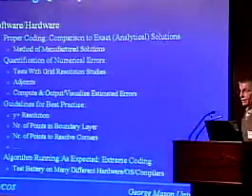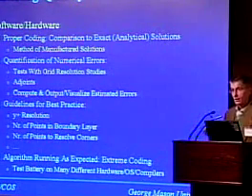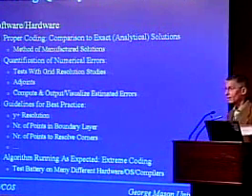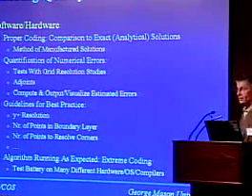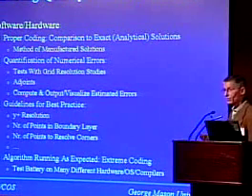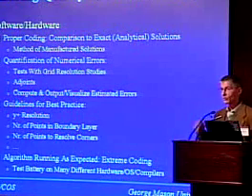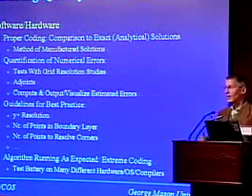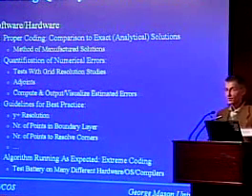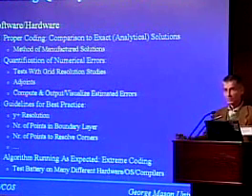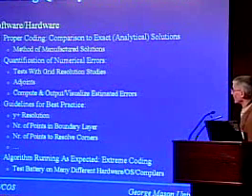So the way that you do this is that you make the mesh twice as fine and then 4 times as fine, etc., until you burst your computer resources and you say that's my converged result. Now in 3D, and I review a number of these papers, sometimes you find people say, oh, we doubled, the number of elements has gone up by 2 and there were no changes. Well, guess what? The factor of 2 in 3D doesn't do anything. You have to be at least 8 times finer before you really see a difference.